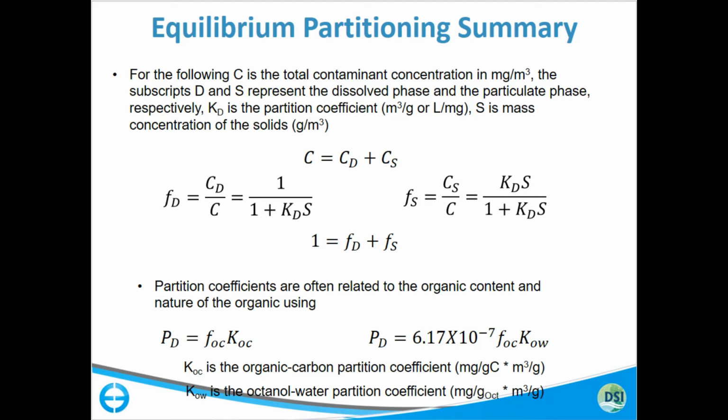So this is a more standard approach to the modeling. A lot of times in the literature, your octanol-water coefficient, KOW, is reported instead of a KOC. There's a relationship of KOW to KOC using that conversion factor, so you can go straight from KOW to your partition coefficient using this approach. You would take the KOW and multiply it times this, and that would be what would go into EFTC. But just so you can see how it works here.